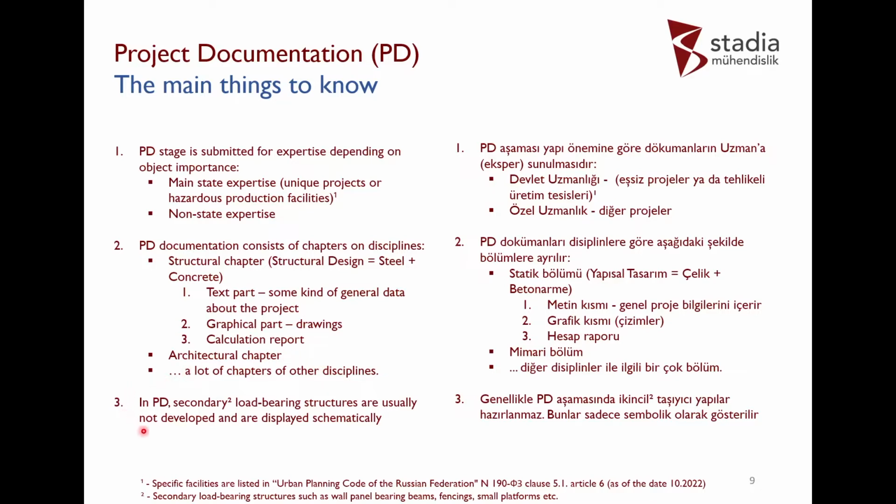The third point is that in PD we should not show all secondary load bearing structures. I mean, for example, if we have fencing, non-bearing panels, small platforms, it's not necessary to show them in project documentation. We should consider them in calculation, of course, but it's not necessary to draw them.